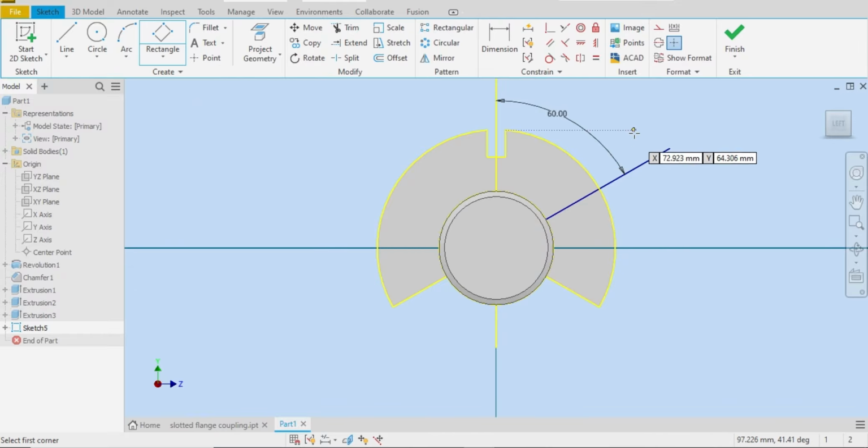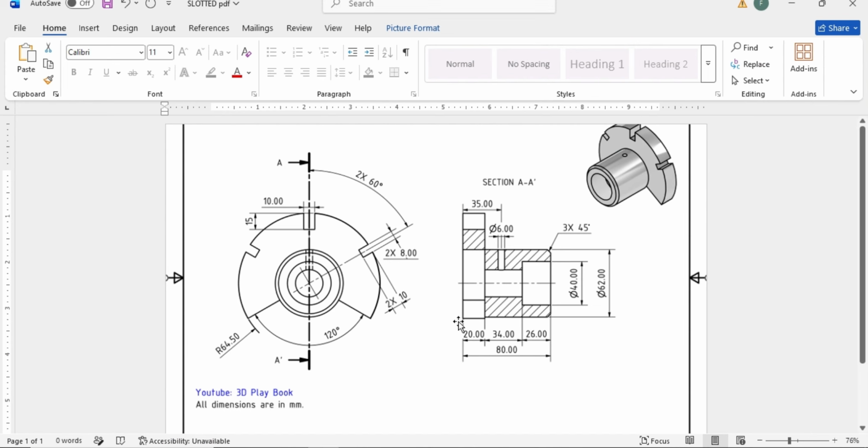Look, line for the 3-point rectangle. Let me select this line like this. Okay, let me select parallel constraint, select this line and this. Okay, now this rectangle is parallel to this line, so I will just simply give dimension. Now let me select dimension to this little sketch. 8 millimeter is the length and 10 is the height.